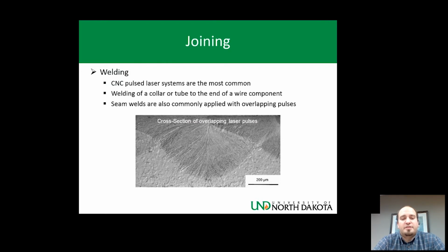Laser, plasma, and resistance welding processes are all commonly used for joining SMA components. The challenge for welded SMA components is the large amount of heat input required to create the joint. The weld itself, as well as the heat affected zone adjacent to the joint, will have different mechanical and functional properties. In laser, plasma, and resistance welding, the fusion zone will have an as-cast structure.